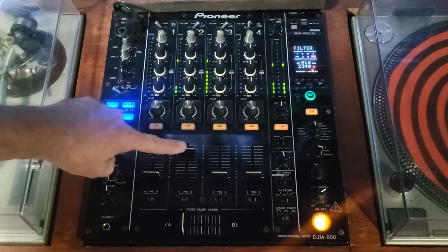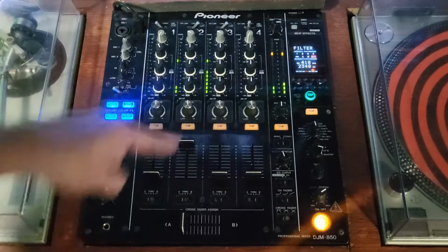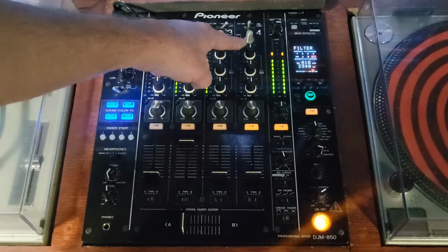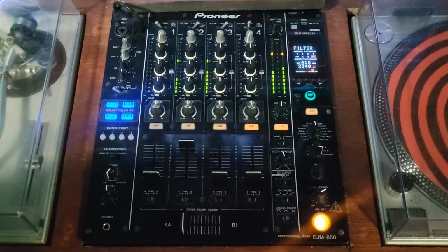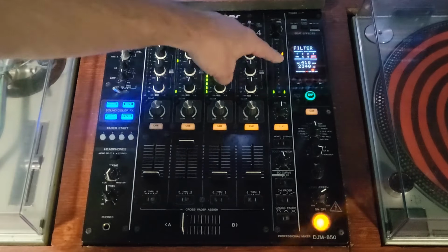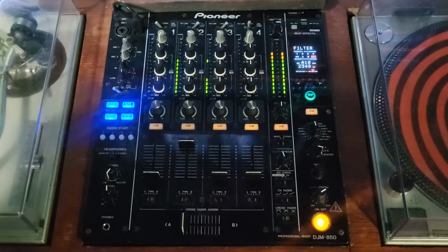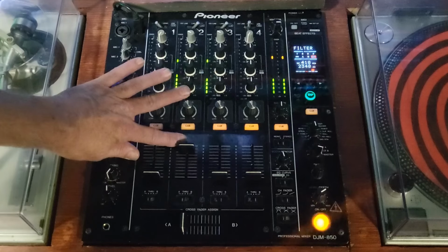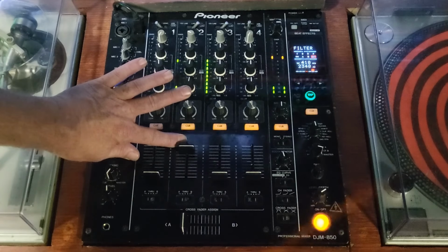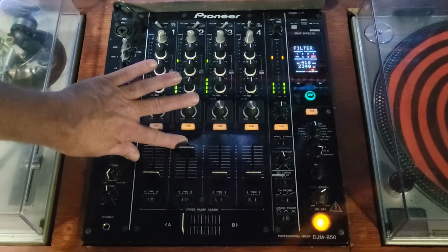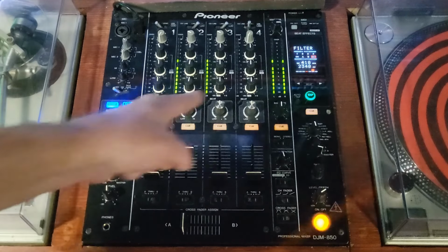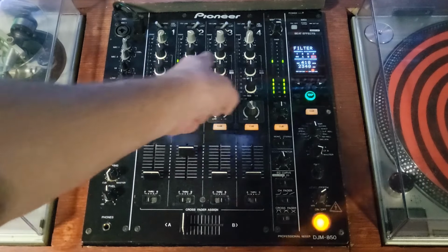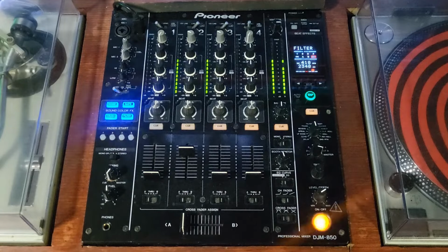Look what happens when I bring it all the way up. We go into the amber, like plus 6 or 7 dB. We're realizing some distortion at that point. We want 0 dB coming out of our master. So 8 is the highest you go on the line fader to achieve that. That's 8 right there. And see what happens? We're unity, 0 dB, all the way across the board.